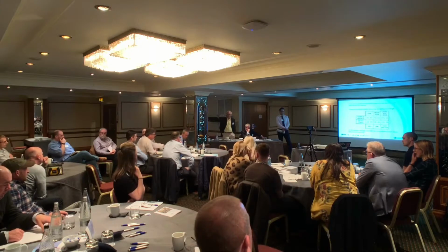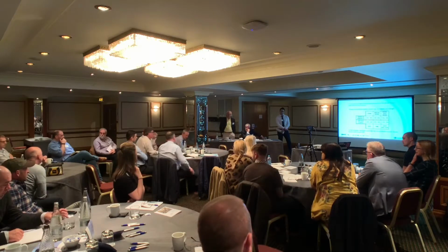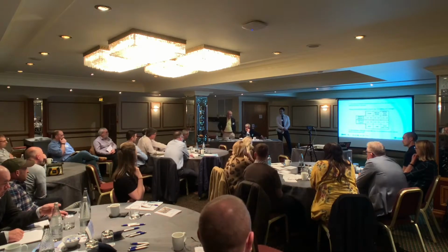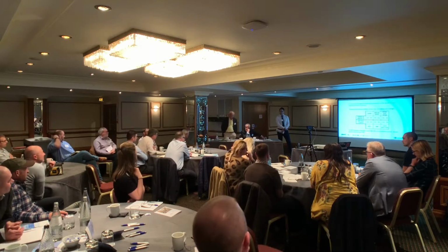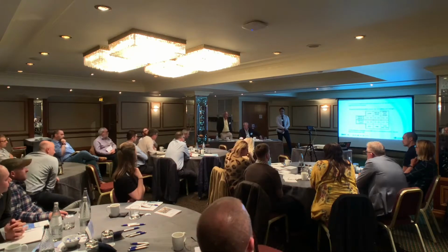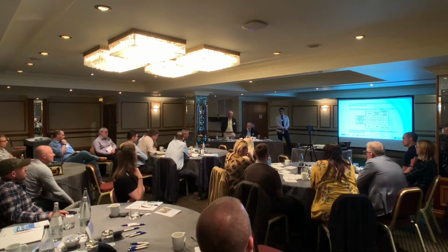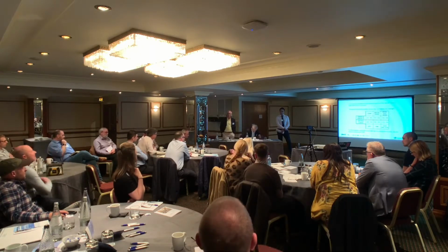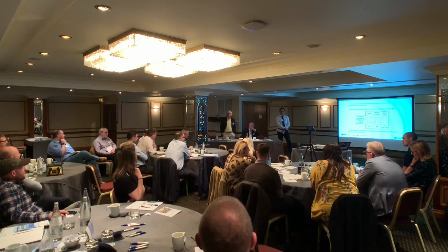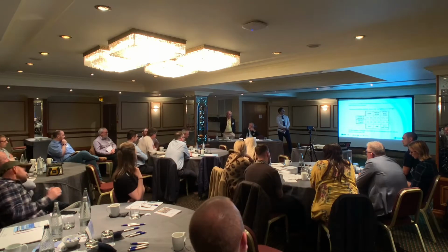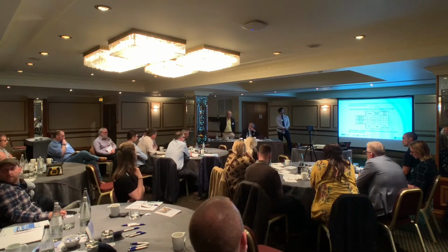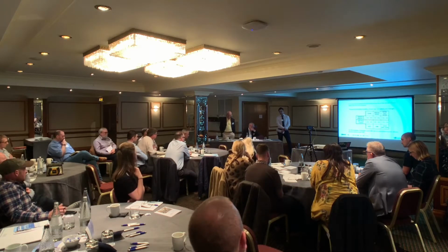Was that in the London clay? Yes, it was. So adjusting the speed of tunnelling will affect how the face pressure balance is controlled. Pick a reputable designer who assesses it conservatively to start with, but can take on board factors, and pick a reputable company who know how to select the correct type of machinery.